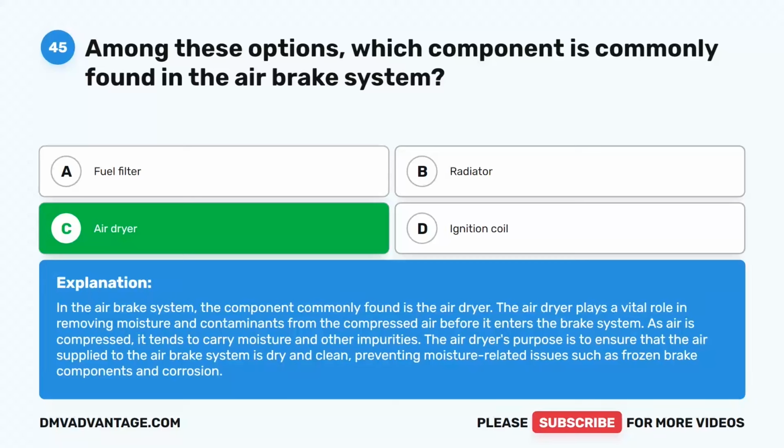The air dryer plays a vital role in removing moisture and contaminants from the compressed air before it enters the brake system. As air is compressed, it tends to carry moisture and other impurities. The air dryer's purpose is to ensure that the air supplied to the air brake system is dry and clean, preventing moisture-related issues such as frozen brake components and corrosion.